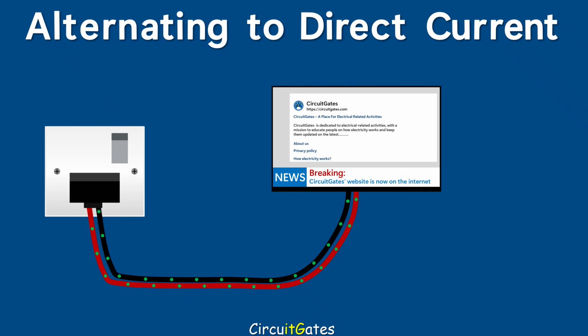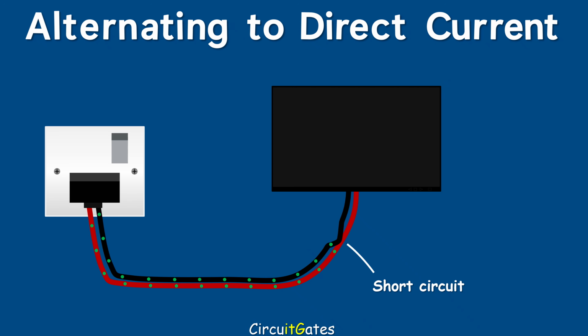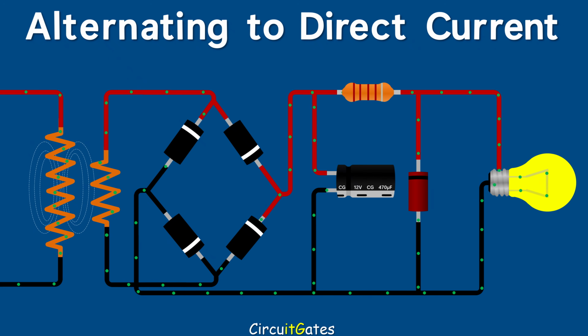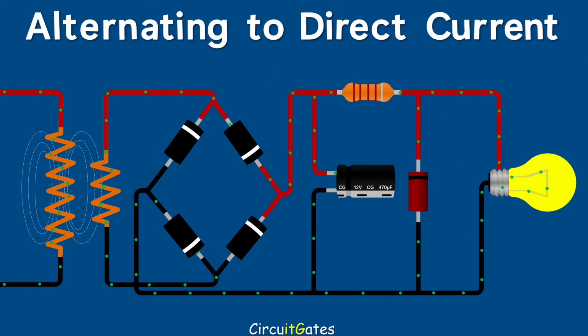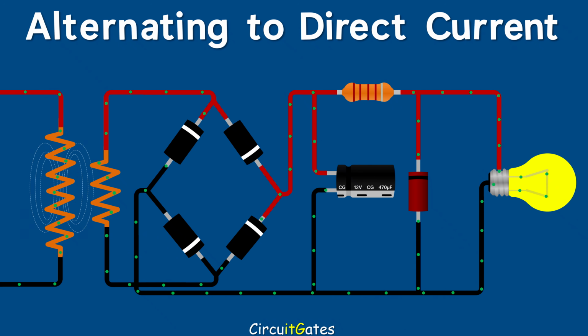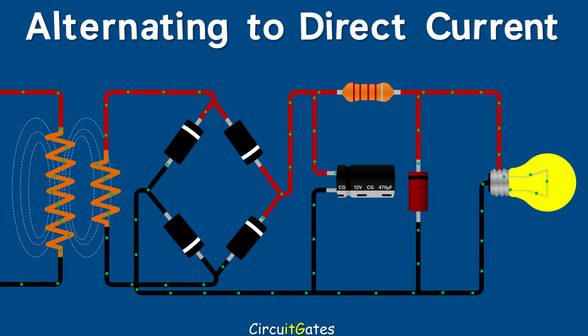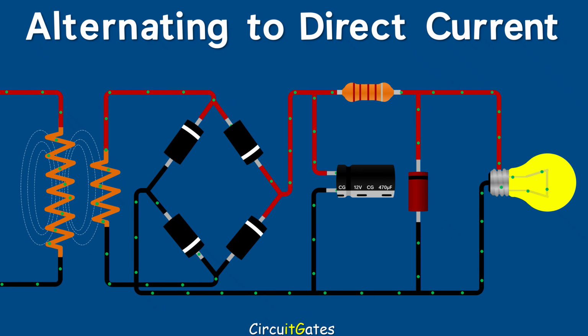What happens when we have a shorted path in an electrical circuit? All the circuit currents and voltages use that path because of its zero resistance. This is what happens in a zener regulation circuit. Any voltage above the zener voltage uses the zener diode path instead of the load path because the zener diode path will have a zero resistance to that voltage, thus maintaining a constant voltage across the load.